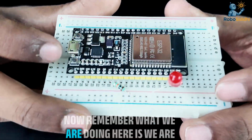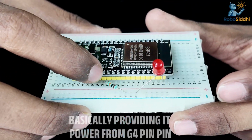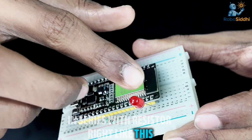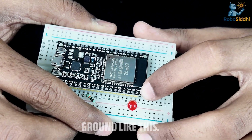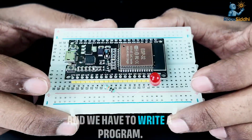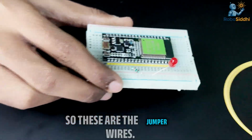Now remember, what we are doing here is providing power from the G4 pin, and then we connect the LED in series with the resistor, like this, and then the LED's cathode terminal is connected to ground like this. So this is the ground pin and we have to write a program. In this case we don't need jumper wires, right? So these are the jumper wires.